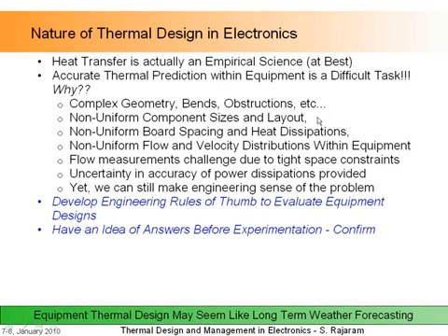Some of those are communications equipment, like I showed you, sitting in racks with boards that are parallel to each other. Heat flow is never uniform. Flow distribution is not uniform. Measurements become a big challenge because you cannot reach the devices. You cannot reach into the junction of the transistor. So lots of uncertainties. On top of that, the power dissipations that the designers give you themselves may not be extremely accurate. So typically what we have done over the years is through experience, we've got a lot of rules of thumb that we design.